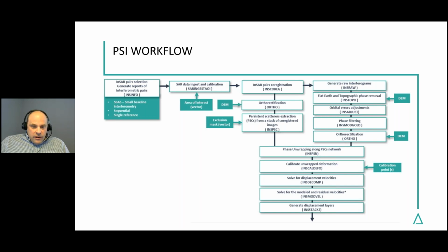If a sensor is supported, this is the workflow that you have, or one of its variations. In input, we accept different input modes, like small baseline interferometry. You can use sequential, or you can use a single reference. So you will usually have one reference in the middle of your stack and you compare the other dependent files to it.